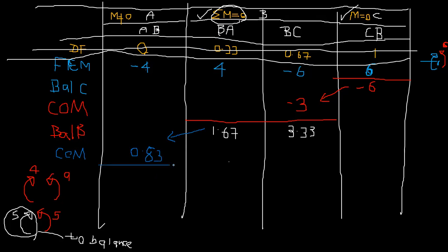So your final bending moments: it is a considerably low value, so it's going to be minus 3.17, and here 5.6667 positive.